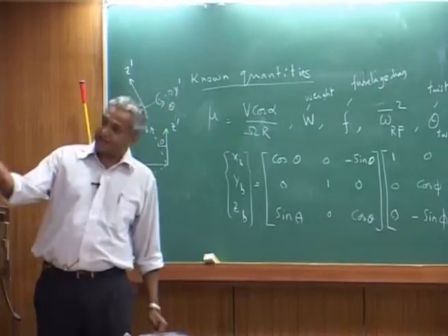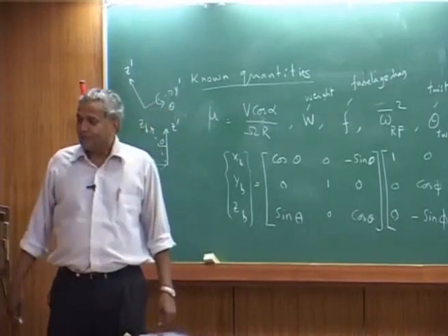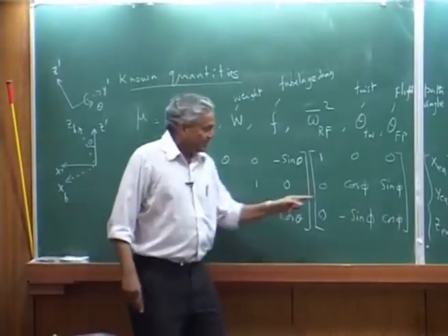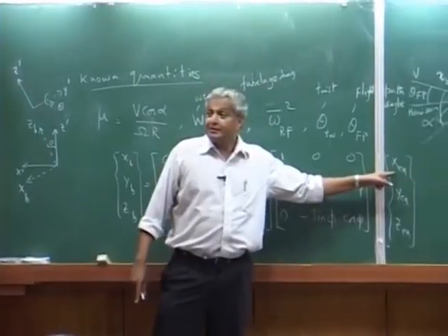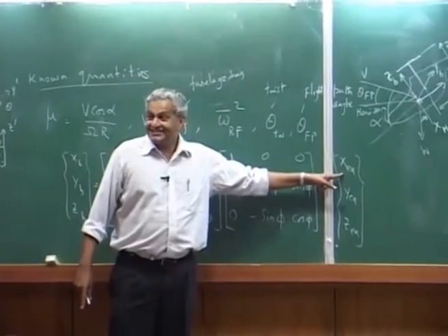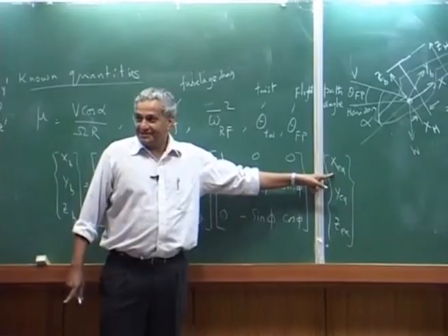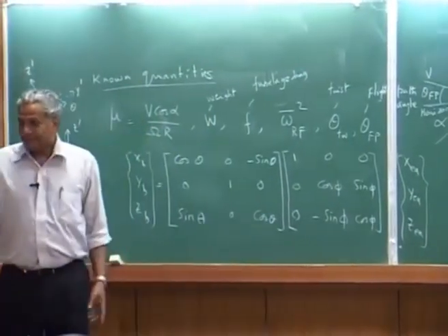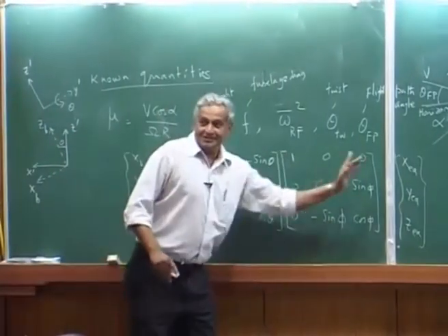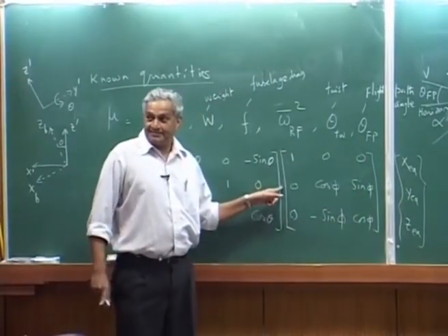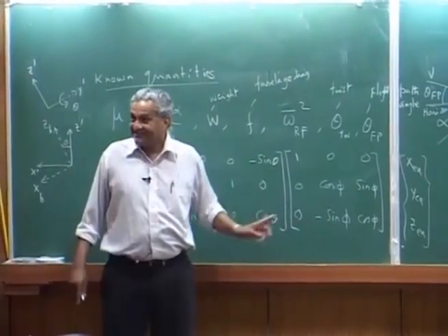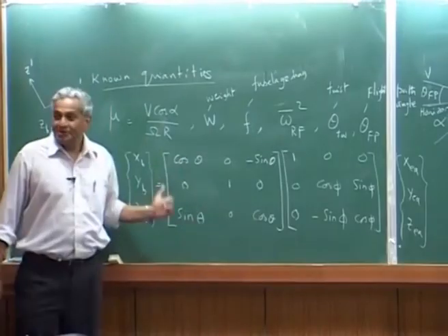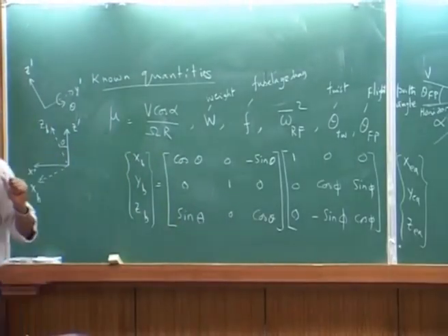So, when I want to get the angular velocity vector, what I will do is, I use the same equation, I will put phi dot here, okay, and then get what is the body fixed phi dot. But then when I come here, I will put theta dot, okay, y prime axis, and then I will calculate what is the effect of that.